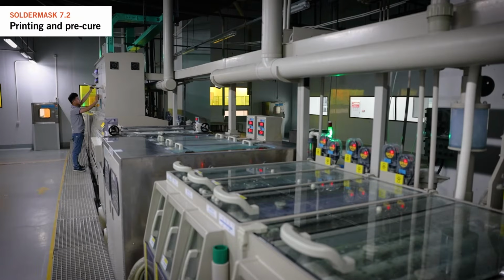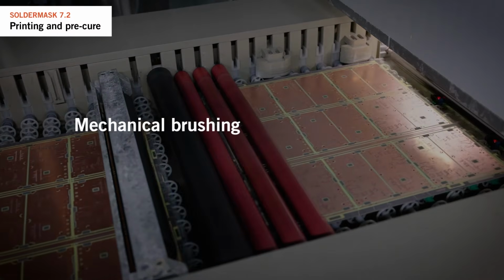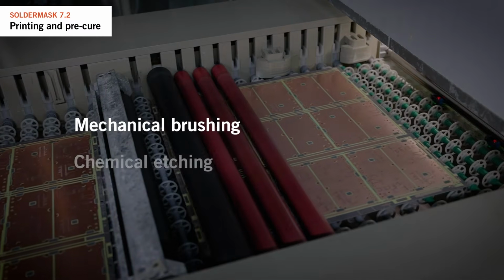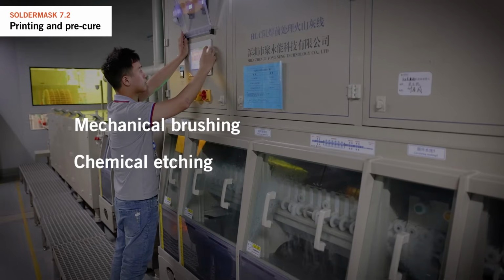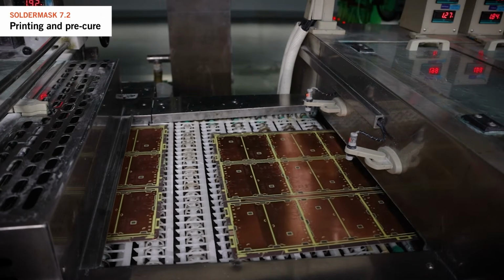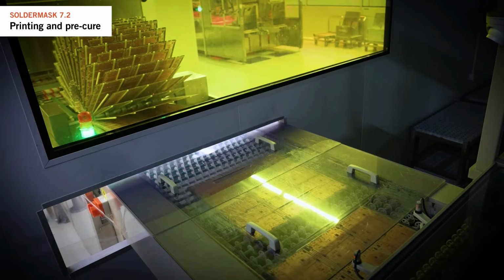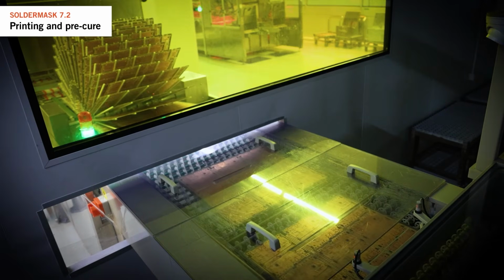First, we need to prepare the copper surface by roughening it for better adhesion of the liquid Soldermask. This can be done through mechanical brushing with pumice and/or a chemical etching process. Etching is good for fine tracks that could be damaged by mechanical roughening alone. After roughening, the surface is rinsed and dried to prevent copper corrosion.